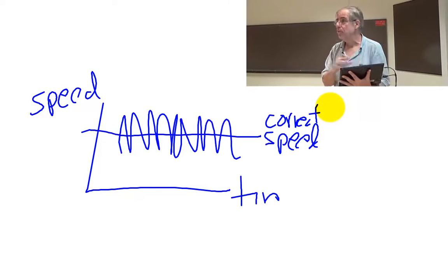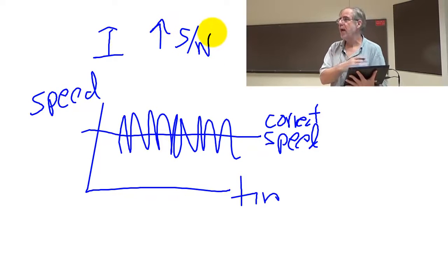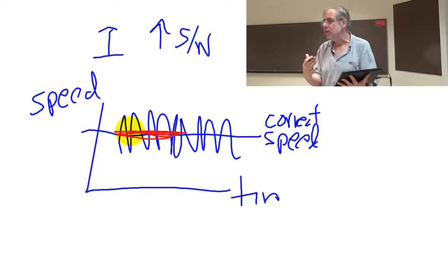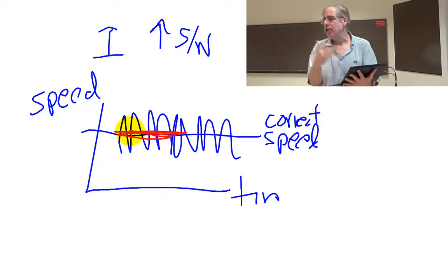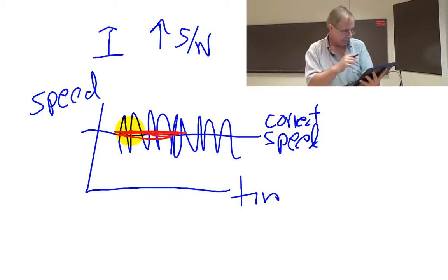The integral term has a much improved signal-to-noise ratio because we're averaging, we're adding them up. And so the average of some points in this loop are indeed much closer to the correct answer. So the integral term here is pretty stable.